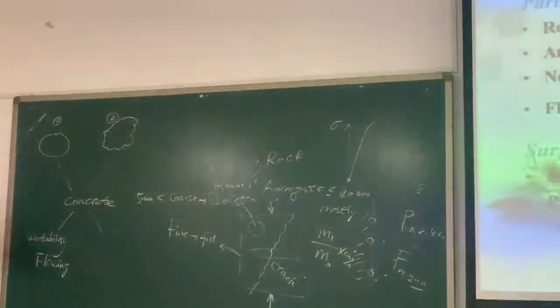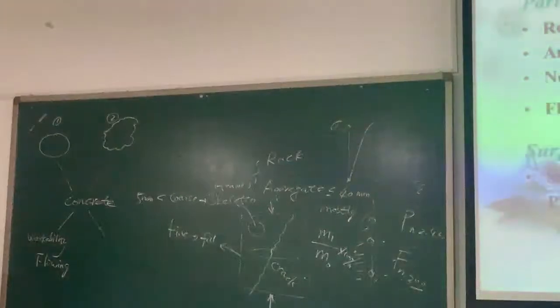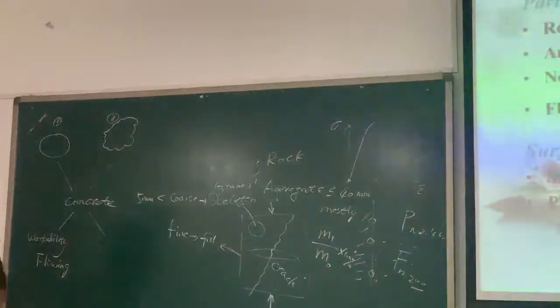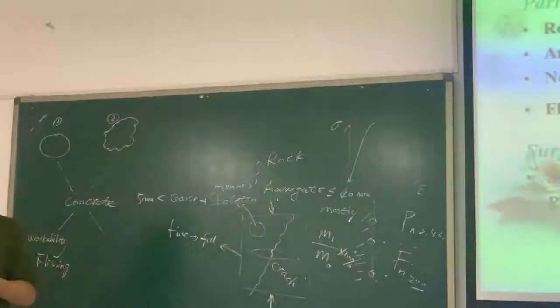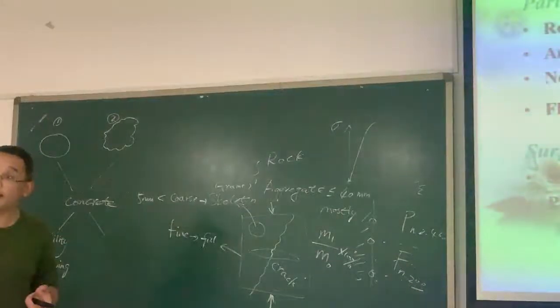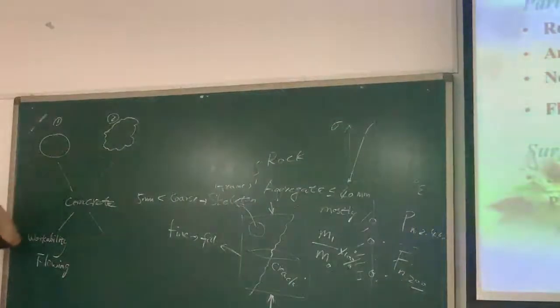The first one. Because you can imagine the particles are round, and the surface is smooth. So it is easy for us to mix them. The friction is small because the particle is round and smooth. So it's easy for us to mix them. Yes, and the flowing property of it is big. But for this one, it will be hard. The workability will be worse.